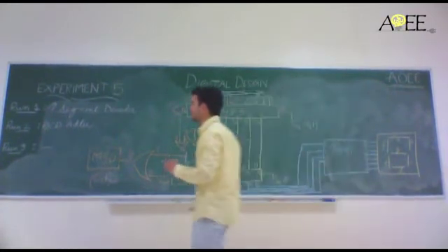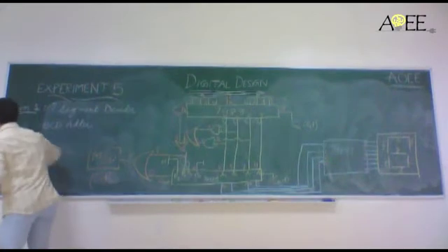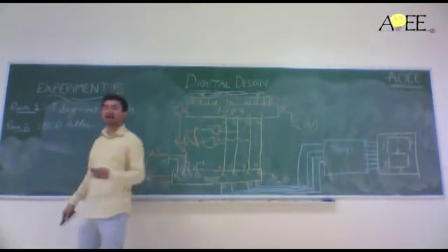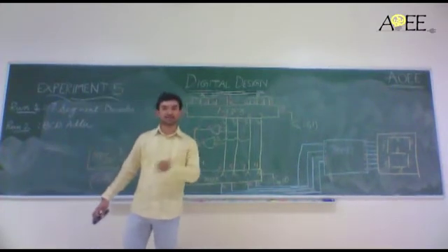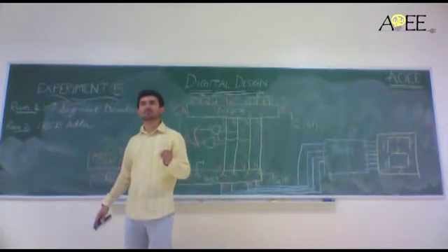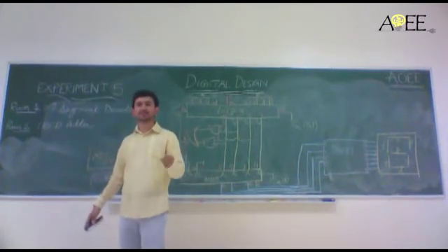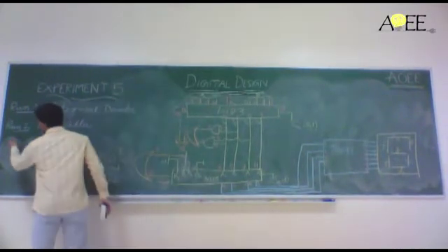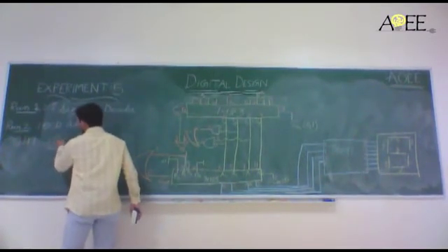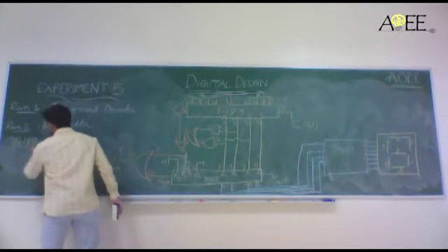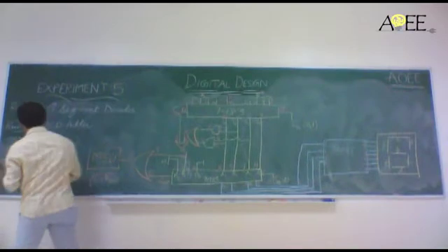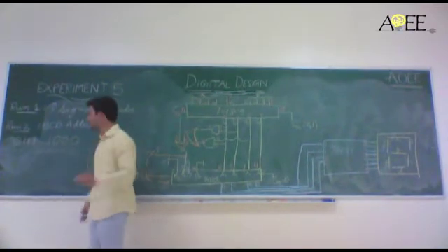Okay, so first of all, BCD addition involves, suppose I am adding 7 and 8. 7 and 8 gives me 15. So 7 is actually 0111 and 8 is 1000. Adding them means they can be added using 7483, but adding them should give me 15.